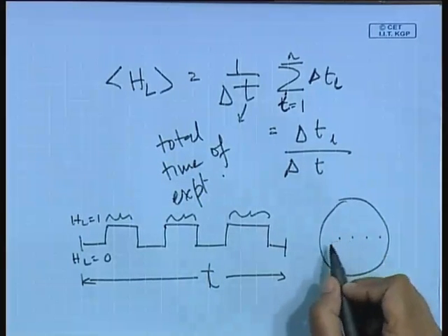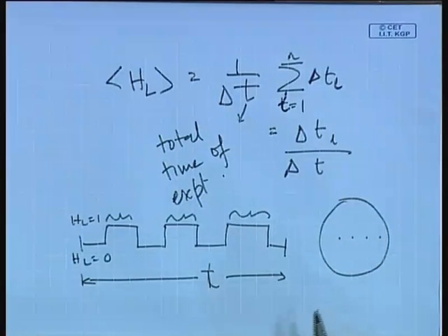So, from there you can find out the voidage profile or the distribution of the voids, and accordingly you can play with it, or you can control it and manipulate it, or you can at least have an idea of what it is, so that if you cannot do anything with it, you can at least incorporate it in your models. Definitely, if it is a parabolic sort of profile and you assume a flat profile, then your results are not going to be accurate.